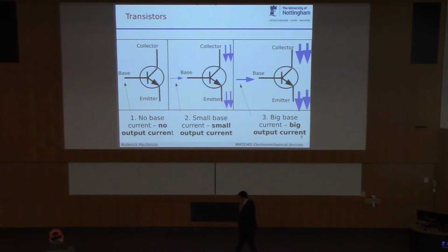Now, the interesting thing about transistors is their name. If you say it in a very long way, it's called a transresistor. What this sort of means is a changing resistance. Previously, we've looked at the case where a transistor was 0 ohms, so switched on, or a mega ohm, or some really, really big value, so switched off. But there's also this state where it's a bit on or a bit off, so it might have a resistance of a few ohms or a few kilo ohms. This intermediate transresistance state is very useful for building things like amplifier circuits and all types of electronic devices that we'll look at now.